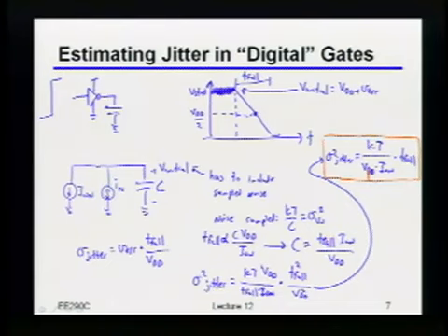It's not exactly power, because in principle you should never have the I_on of the NMOS transistor flowing through VDD. But dimensionally, that's how it looks. The higher the VDD is, or the more I_on your transistor has, that implies you're driving more capacitance. Basically, increasing the power consumption is something you'd have to do if you want to knock down this sigma squared of the jitter.